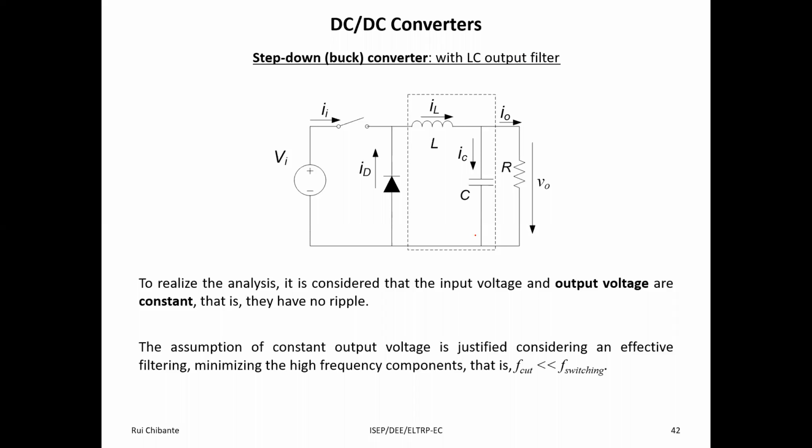In this converter, of course, in terms of the power that we have at the source and the power that we want at the output, and as a function of the currents and voltages present in the converter, we must choose an adequate transistor and an adequate diode that support those currents and those voltages.